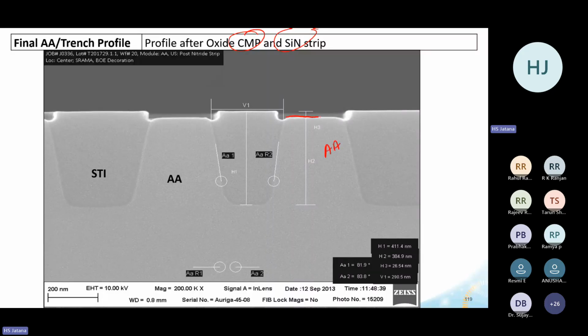So this is oxide, which was 188 angstrom. It remains on top of here. Earlier silicon nitride also was there. So I have removed silicon nitride here, and here silicon dioxide is there. Whatever silicon nitride was there, I have removed by etching, and that is how I am getting a divot like this kind of thing. This kind of divot I will get.